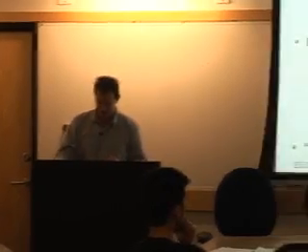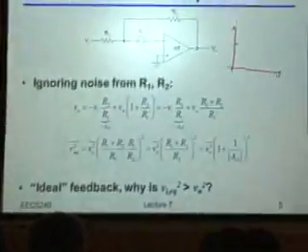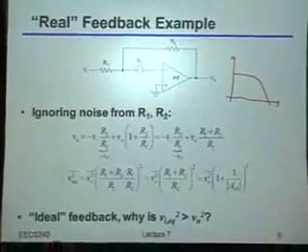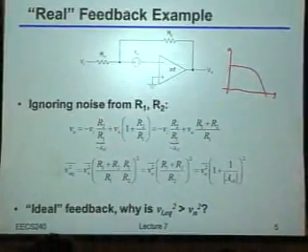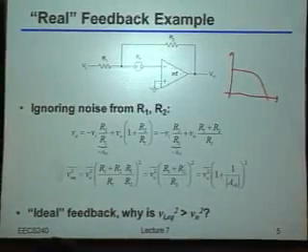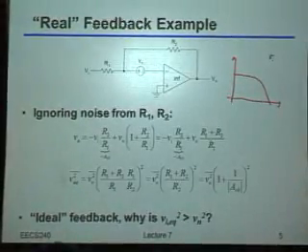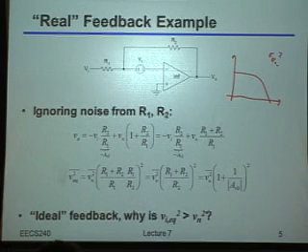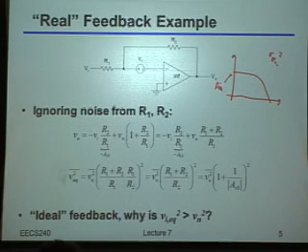The reason it's done the way it's done is, let's say you had some amplifier that had a transfer function that looked like this. Typically, if you were to do the input referred noise from an integrated standpoint, you would find the total integrated noise at the output, and then divide it by this DC gain squared, at least in the variance.